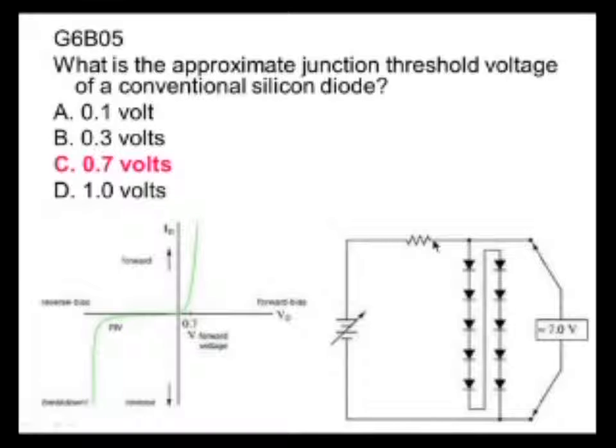The resistor, because of the increased current here, will control this at 7 volts out here at the terminals. Now, that's kind of a crude way to do voltage regulation, but I've actually used circuits that do it that way. The silicon diodes will conduct at 0.7 of a volt. If you have 10 of them in series, then you have a 7-volt regulator.